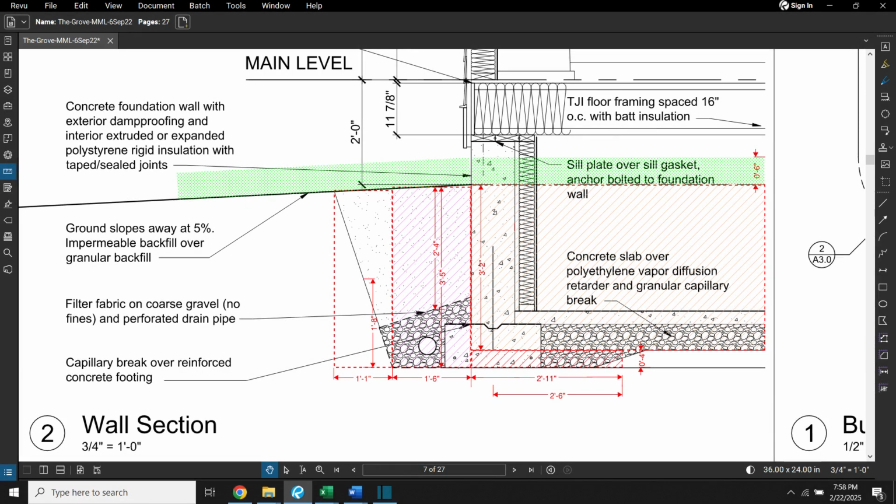Now, let's examine the excavation needed for the drain trench. The trench has a complex trapezoidal shape, and the site has a gentle slope away from the building. To simplify the quantity calculation, I divided the trapezoid into two vertical rectangles. The first rectangle, labeled cut for drain trench slope, covers the acutely sloped side of the trapezoid. Since only half of this triangular section is removed, I applied half the rectangle's height, 1 foot and 8 inches, when using the volume markup tool.